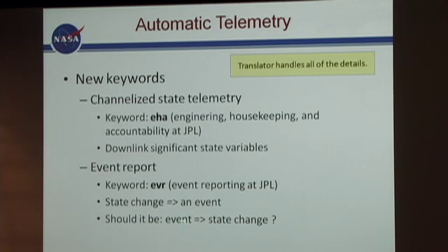If there is an event like that that's important enough, the thinking may be, well, maybe we ought to trend that and find out what it looks like over time. So we can see if we have a fundamental control problem or there was an error in data or something like that that took place and it was just a momentary blip. But if you're going to trend something, you're going to have to keep track of it, which means you have state. So immediately, if it's an interesting event, it sounds like, more likely than not, there might be some exceptions, but I'm going to bet that it's worth keeping track of, and therefore the event will be reported because there was a state change.